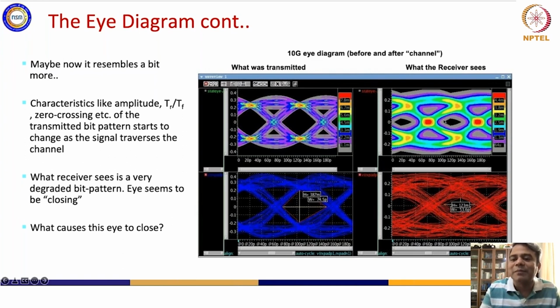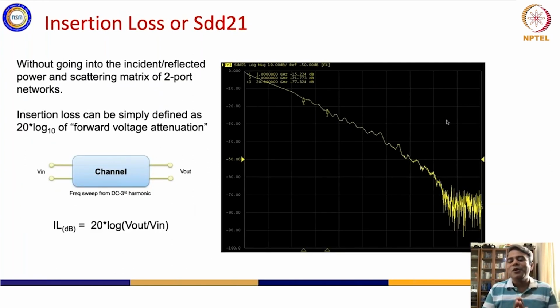What defines this fundamental limit? This is where we come into. So I'm getting into what the limits are right now, or why we have only 10 Gbps. Why can't I make 1 Tbps today? The reason is that I have a certain media, and it has certain kind of loss characteristics. Every media has frequency dependent conductance.